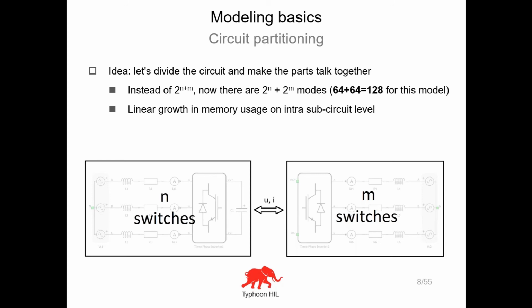So we have effectively linearized the problem. As a result, we have significantly reduced the memory footprint and added an option to parallelize the model execution. So with this approach, we are reducing the memory requirements by significantly reducing the overall number of modes, and we're also shortening the simulation step by computing the smaller subcircuits in parallel.